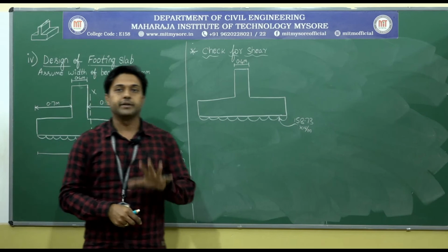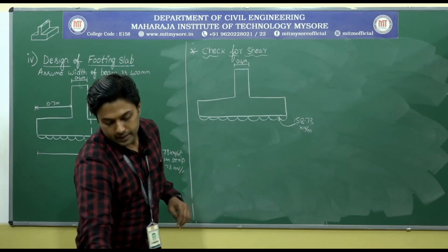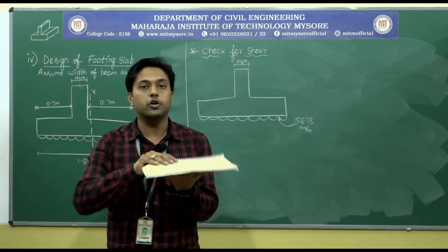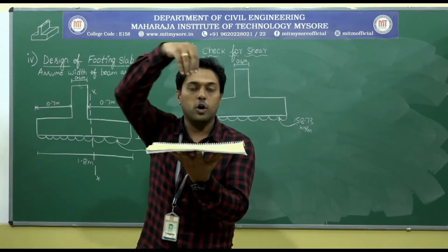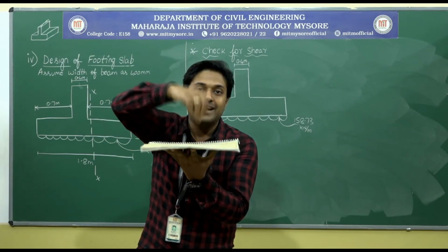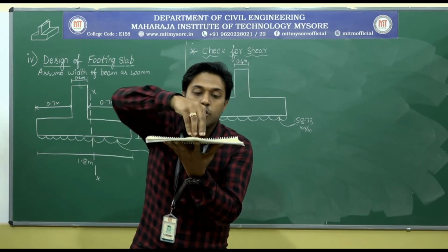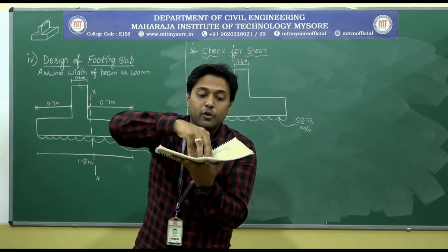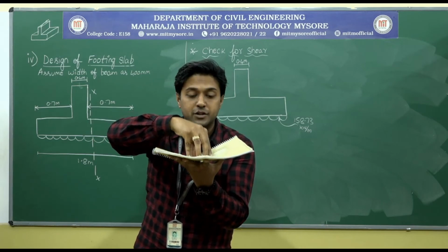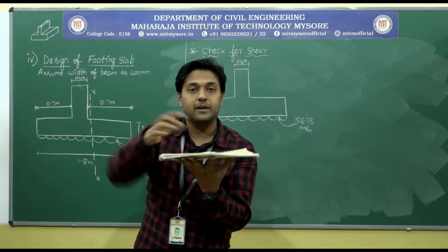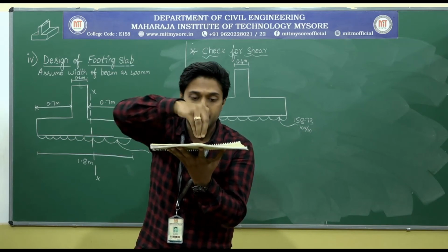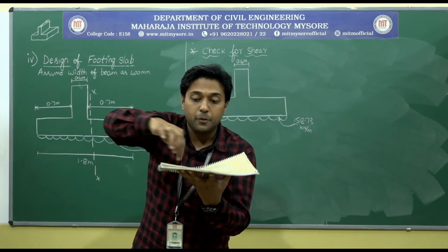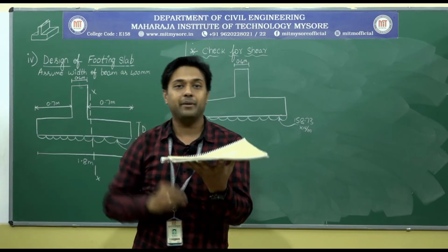Okay. So please remember one thing. Shear, whenever a footing is loaded by the column, when column exerts load onto the footing, it punches. So where the point of contact of the column is there, that will not be subjected to rubbing action, but apart from that particular portion, observe, whenever I am pressing this, don't you see that the other portions of the book are getting lifted up?